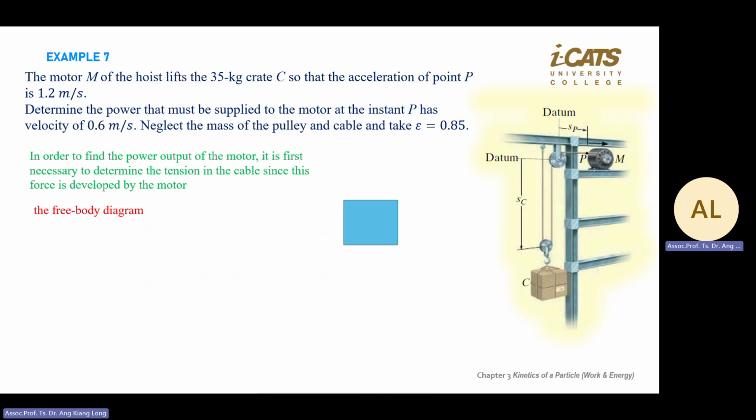Okay. In dynamics, usually you need to draw a diagram. For C, you have a pulley, so you have two tension cables and one tension cable going down. So you draw the free body diagram for the package with the C. Free body diagram always starts with W at the center of the object. W equal to mg, and once you solve for W, the second step is to put in the external force.